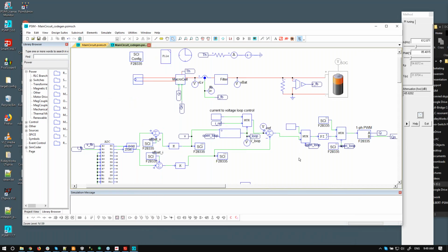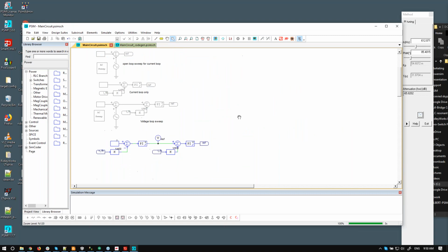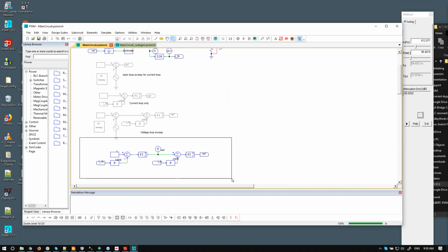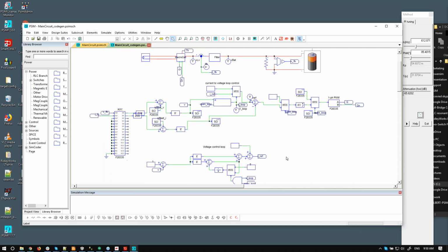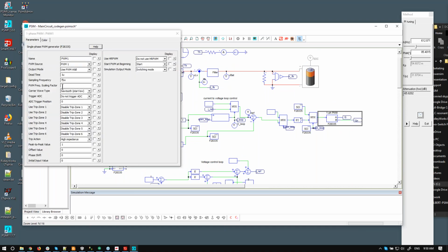And then we've also then run over to the closed loop form with code generation. So this is the real fun trick here. So now what I've done is I've digitized that simulation. So here where we have the PWM, the controller, I've wrapped that in PWM target files for the F28335. So this F28335 output block here, we're defining the switching speed and the dead time.